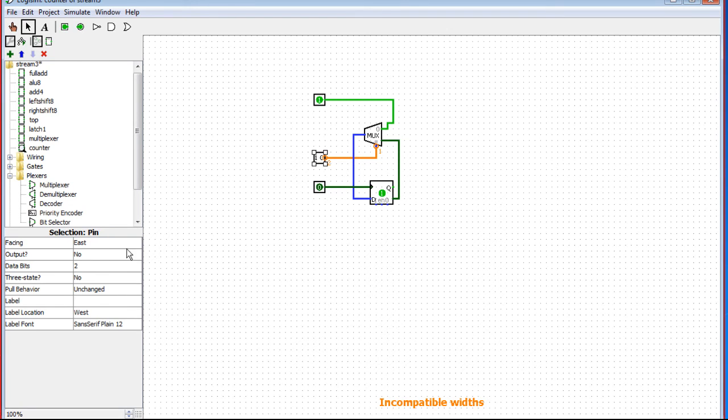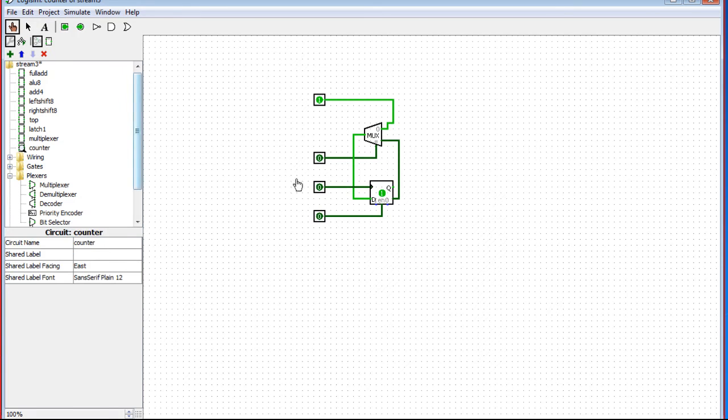And we're going to go here. All right, this is better. This is much better. Now we're approaching something that is sane. So what we've got here is, let me think here. This is the toggle selector. So if we have this true, every clock cycle. You're making a liar out of me. Wait. This thing doesn't have not Q. Wait a minute. No, it does have not Q. This is 1. This is 0. Oh, because I didn't turn the enable on.